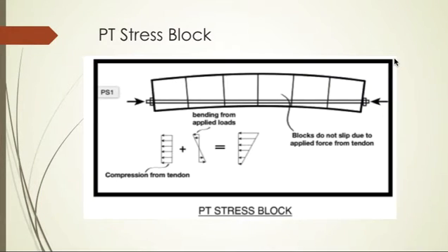So the introduction of pre-stress, post-tensioned slabs allows for greater spans and a reduction in depths of the concrete slab. The prime reason for introducing pre-stress into the concrete beam is to improve the service load behaviour. Before the service load, the pre-stress tendon induces a force on the concrete that produces the initial upward deflection. As we can see here, the neutral axis is brought up, so the range of uncracked behaviour is significantly increased.